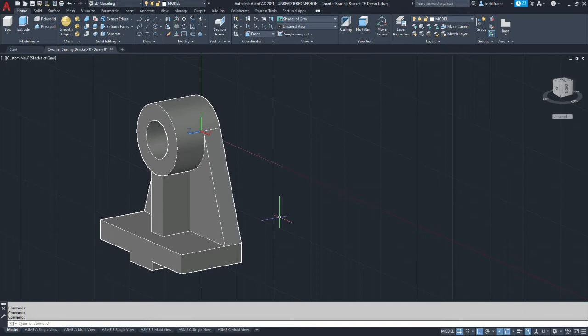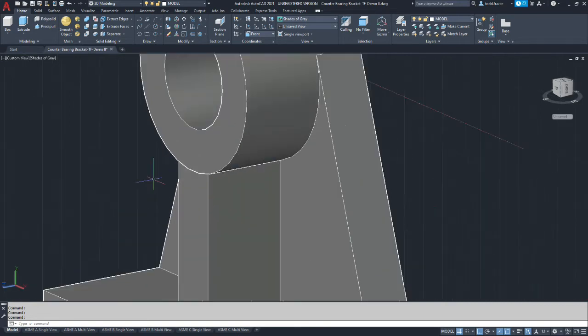And there's a couple ways to approach this. I'm going to draw it on the side of the existing model web that we've made, but there's a way to put it on with draft. There's all kinds of ways of doing this. The downside of what I'm going to do is it's going to create a little piece of material we're going to have to remove later that will fill in that chord area that I was talking about.